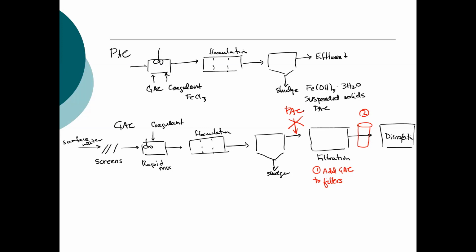What was the parameter that we used as a major design parameter in designing filters? And it controls the depth of the filter. Okay, we use turbidity in determining our backwashing, but what calculation did we do? We spent a significant amount of time on it. So we use turbidity to control when we backwash. What's the other parameter we use to control backwashing? Exactly, head loss.